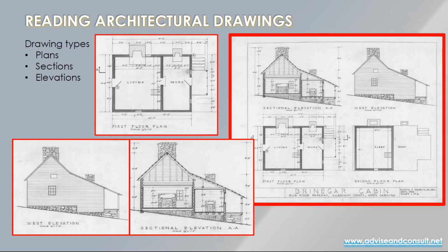But you can see, for example, that the fireplace, if you look at the plan, the fireplace is at the back of the building. But then in the upper right corner, the west elevation shows the fireplace chimney as if it's in the same plane as the elevation of the building, which in fact it's not. Again, you would never see this with human eyes. You would be standing in front of the building and that chimney would be quite far away from you and you wouldn't actually see it. So that illustrates why elevations are important, because, for example, you want to show how far above the peak of the roof line that chimney occurs.